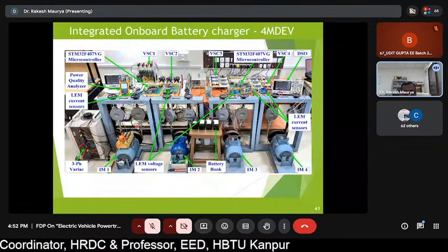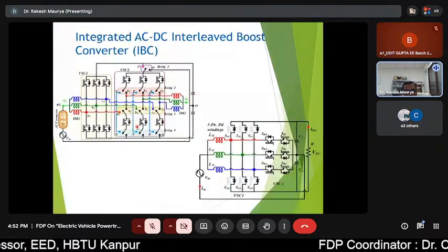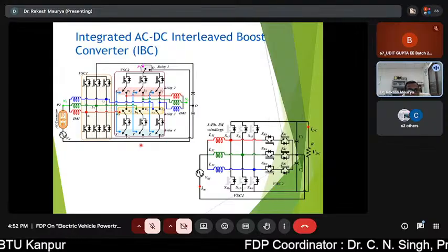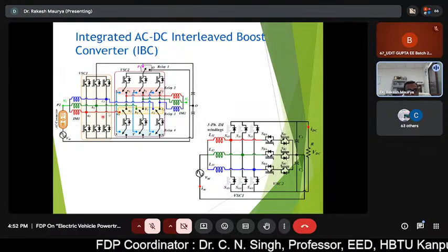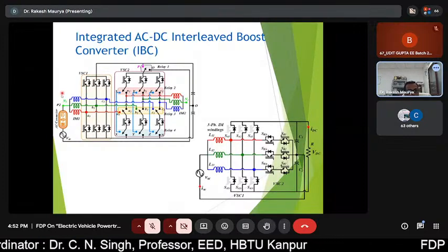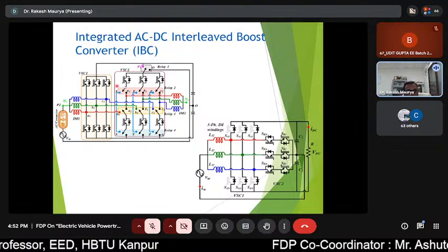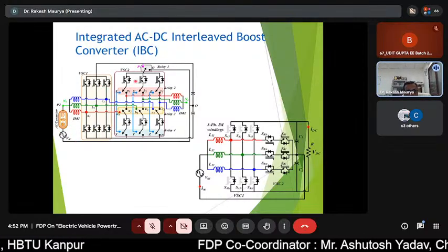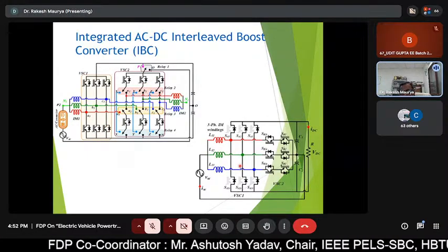There are a variety of PWM rectifiers, like the three-phase PWM rectifier. So there may be a Vienna rectifier. You might have heard of the Vienna rectifier. So can we use these two wheels, meaning six switches, configured to make the Vienna rectifier here? That can also be done, and we have developed and tested it.